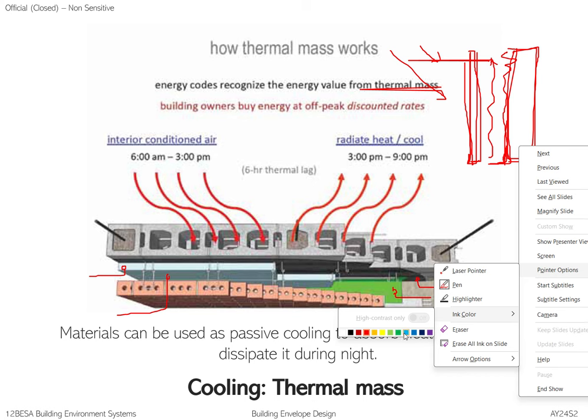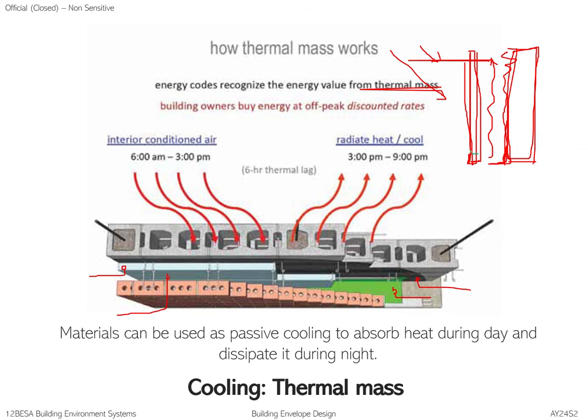So usually there will be a ventilation opening provided right here and at the top, to allow the hot air to dissipate. And you must have a weep hole at the bottom as well for the moisture to come out from the cavity within the wall. In building, one of the scariest things is to trap the elements within the gaps. We don't want to trap air in any gap. We should create allowance for them to move in and out of that space.